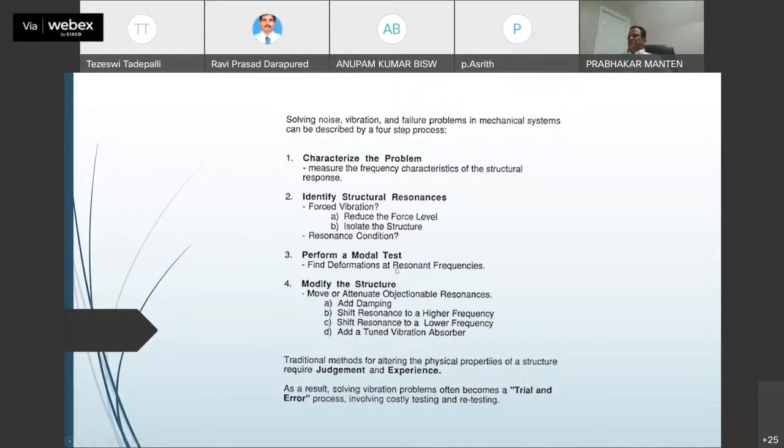If any of these resonances are coinciding and it is creating problems, either move or attenuate. Attenuate means if you cannot move the resonance, sometimes you can condition it, bring it down, reduce it. How do you do that? Add damping. If it's unavoidable, then add additional damping parameters, not too much, don't overdo it, but take a look at it and see whether that would help.